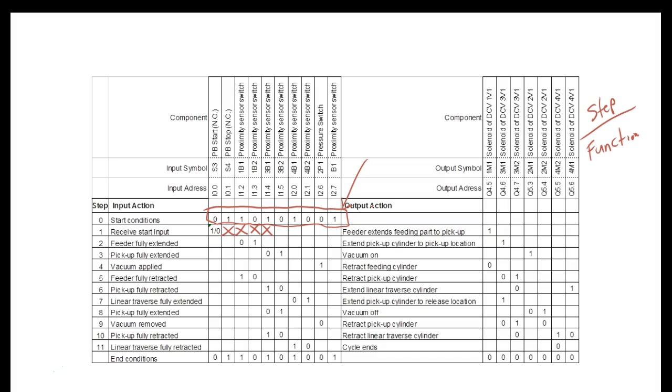Now, the more complicated they make a system, the more expensive it's going to be. Okay, y'all understand that? So they're going to go between feedback, non-feedback, or open loop, closed loop, and they're going to decide which one is required to do what. It's just like when the robot goes over there and we reset it and it goes up there and puts a spring down there, it has no idea another spring might be down there. Right, understand? And we do this on the Festo line too. If there's not a piston over there, if there's no sensor over there, the robot will spin around and go over there and what? Open its grip or go down there and clamp down and come over.